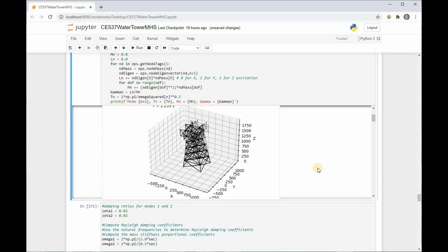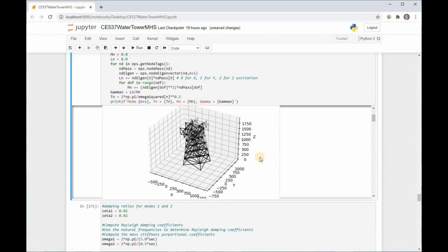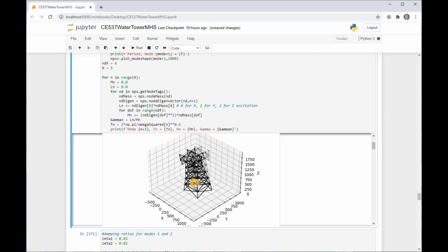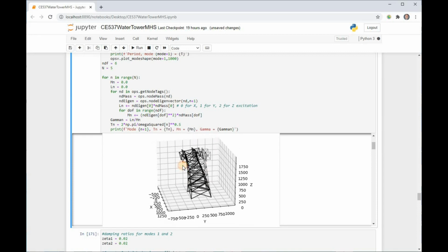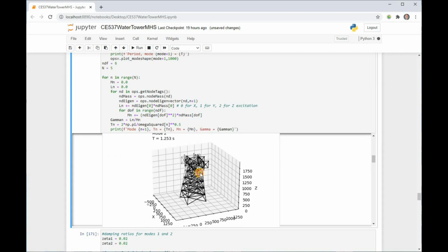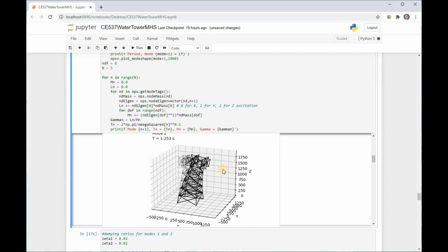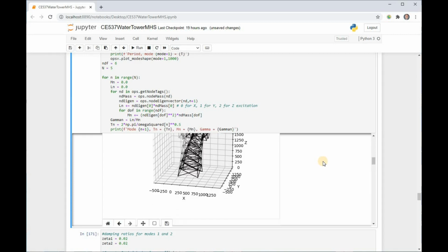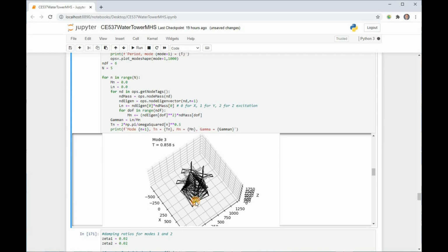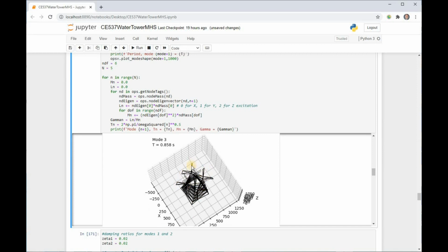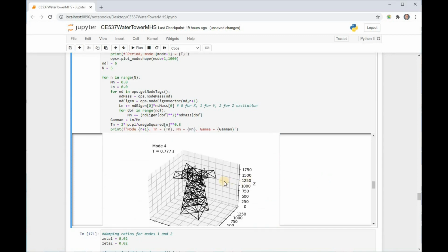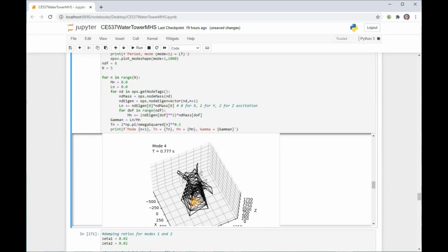Okay, so we'll start at the top. I did spit out 6 modes here, but mode 1 is flexure in the global y direction, as you would expect. All right, that looks fine. All right, mode 2, symmetric structure, so it's the same thing happening in the orthogonal direction, along the x-axis. Mode 3 is torsion. Okay, but you can see there's some distortion within the top of the tank, right? Because we don't have the constraints in force or rigid diaphragm or shell elements or anything.